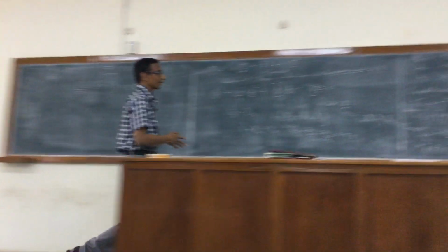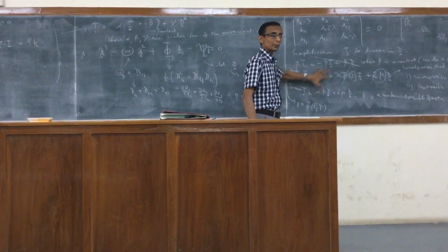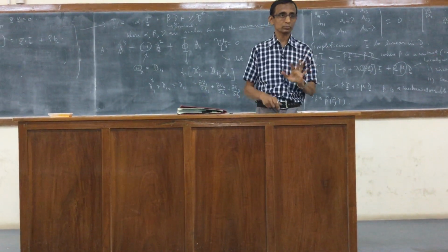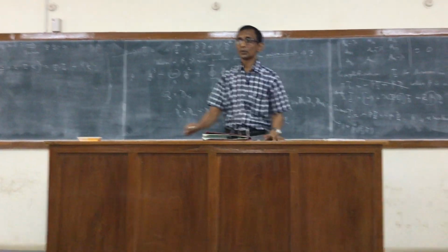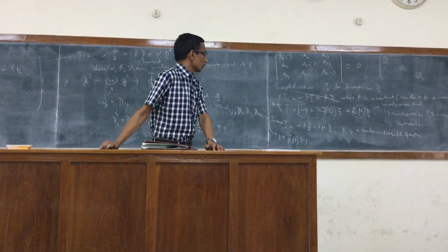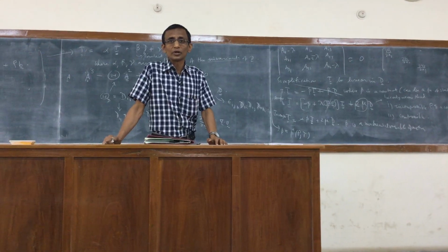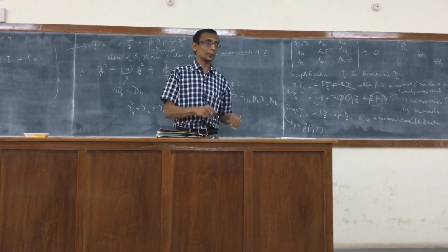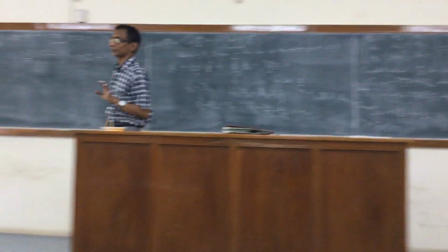Right? So in that case, I have to have this term. However, for the incompressible fluid, that term is anyway 0, so I am left with just this. So is lambda the dilatation viscosity? Yeah, we will take a look at that later. Lambda plus 2 mu by 3 is the bulk viscosity. It is often taken to be 0. For all practical purposes, lambda can be replaced by minus 2 mu by 3. It is what is done.